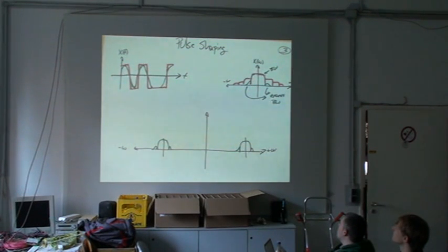You're going to do that with something called pulse shaping. Red is the original square wave, and green is the pulse-shaped signal. It's basically a low-pass filter, and that low-pass filter eliminates these side lobes. Here's your resulting modulated spectrum down here. Now you always have a little bit of excess bandwidth, so there's a little bit of a side lobe hanging off there, but not nearly the problem that you had before.